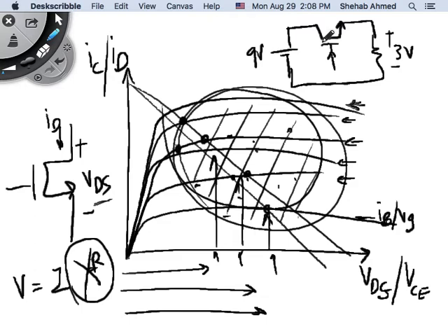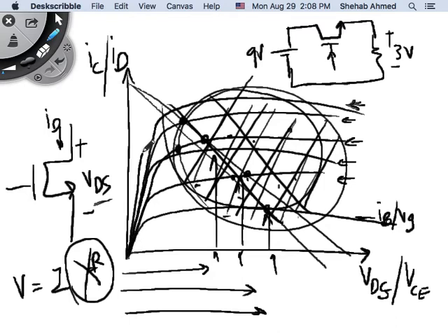In power electronics, we don't operate here at all. We use the same devices, but for the MOSFET, we operate in what we call the triode region, and cutoff. For the BJT, it was called saturation and cutoff.